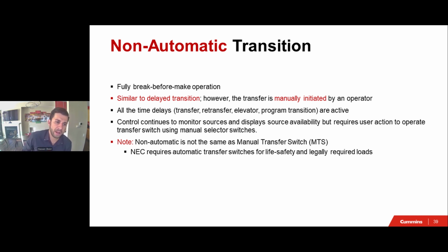The advantage of this non-automatic, and it's different than a manual transfer switch, is that in here, all the protection, all the intelligence that I described, everything that led us to slide 36, is all in there, right? But the transition is initiated manually.